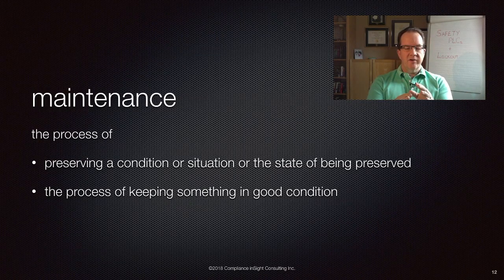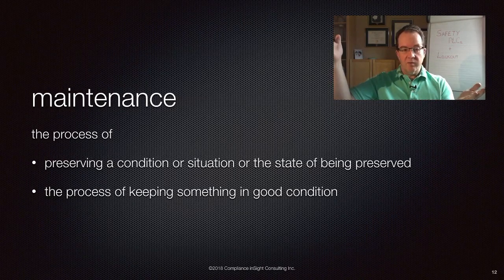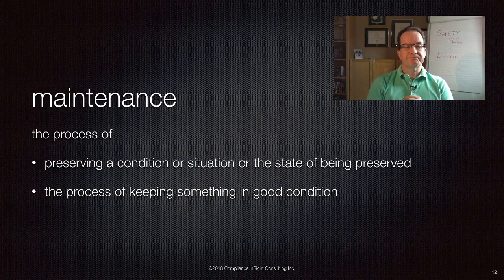And bear in mind here, I've been sort of focusing on the electrical disconnect and so on, but we're talking about any source of energy. So this could be gravity, steam, water, anything like that. Counterweights, that's gravity, but basically any source of energy that you might have. Could also be chemical energy, or solar energy. Locking out solar panels has actually become kind of a thing. It's a difficult thing to do if the system's not designed well, because obviously you can't go up and switch off the sun. That would be a little bit difficult to do.